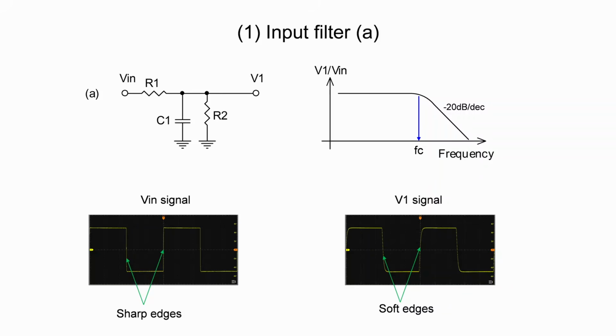What will happen if the input stage is overloaded? If this happens, one or more transistors in the input stage are saturated so that the input stage is pushed out of the active mode. The input stage stops operating momentarily. Therefore, the result is a very distorted output.